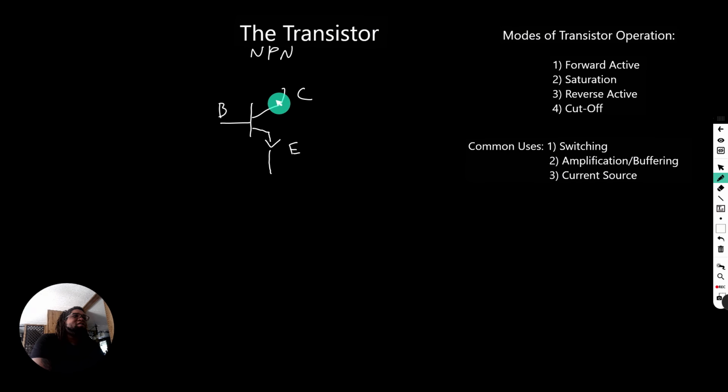this transistor basically has these three different nodes that are typically going to be used in this fashion. We'll have the collector. It's typically going to be our output. The base is going to be our input. And the emitter's going to go to ground. It's basically like a ground reference. I mean, there are all kinds of things that happen with the emitter with respect to the base and with the emitter with respect to the collector. You have to remember this is all relational.